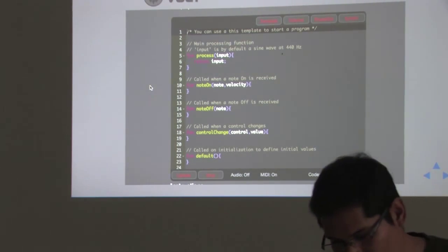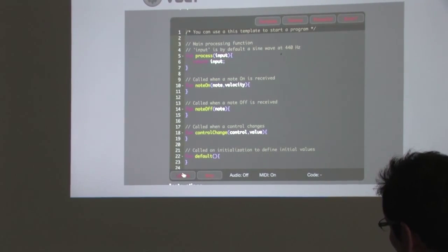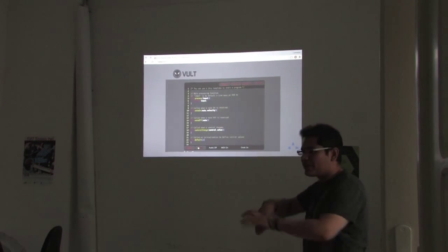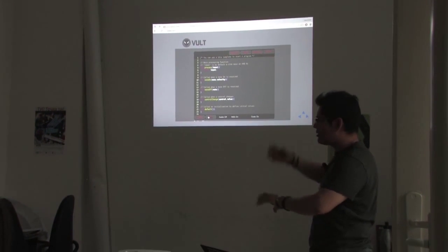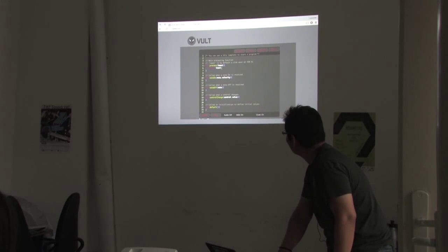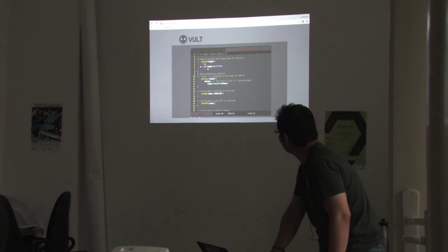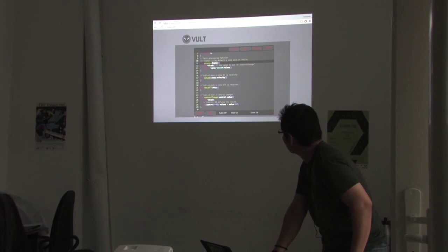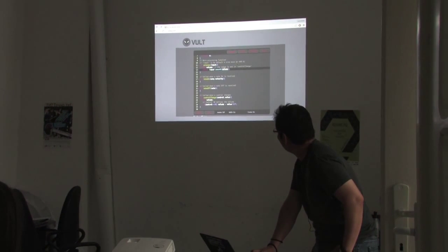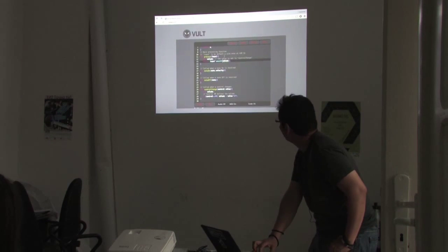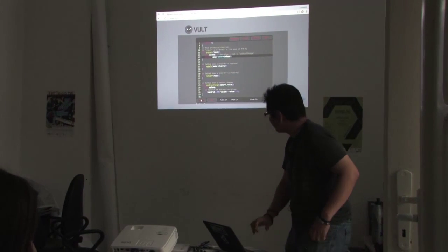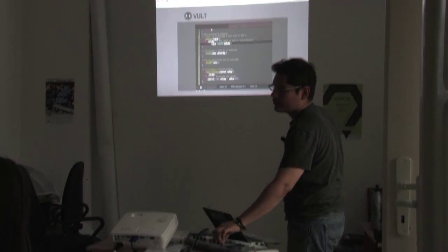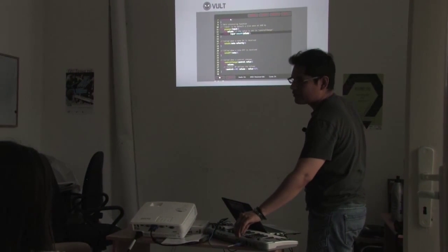Just for testing, I have a sine wave which I'm generating externally, and it's passed in. If I want to have a volume control, my process function receives input, and I have a volume parameter, which I multiply by the input, and then I can control it with this. And input is again a single sample. Yes.